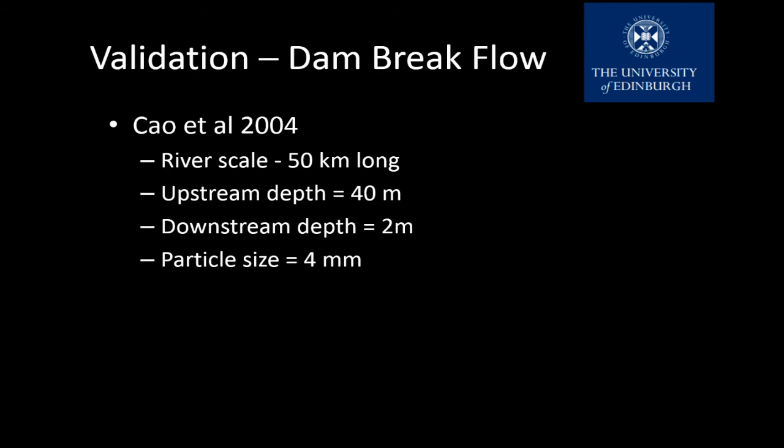So now some of the more interesting results that I've obtained. I'm just going to present 2 of the cases that I've looked at, and both of them are dam breaks. One of them is a simple, well, not simple, but more simple dam break. It's a uniform dam break, so the entire dam across the width of the channel is removed at the same time, so it's a little bit like a 1D dam break, and the entire bed is erodible.